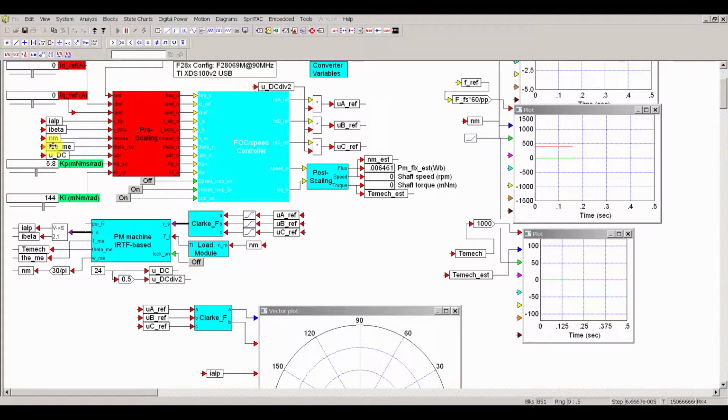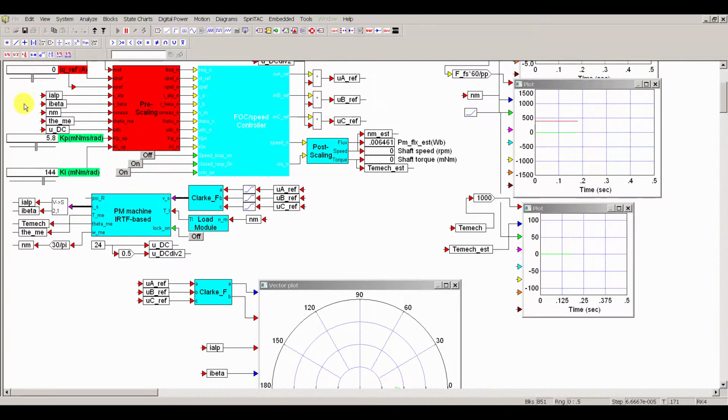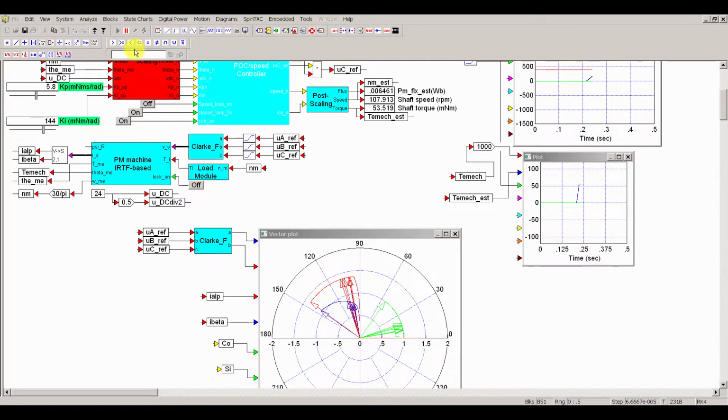and now observe when I put a current in at 90 degrees to the flux. Stop it quickly. You see now that we have produced a current vector, the red one, at 90 degrees to the green, where the flux is. We now have torque, physically torque. We are now producing torque.